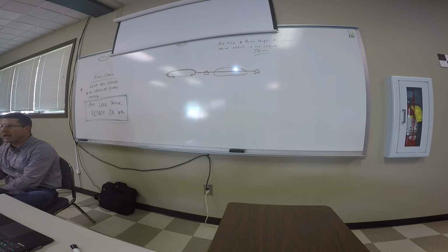So what I do is Carlson can be set up to have companion codes and so forth. So if you call something PBX, I'll make EBX work for it also, and it'll bring in the same little symbol for it. We also have PowerPed. Nobody ever shoots PowerPeds. We've had the discussion as to, we have TPED or CPED. TPED's the old code, telephone pedestal. We quit getting that specific on our utilities and just went to CPED for communication instead of trying to identify it as something other than telephone or cable TV.